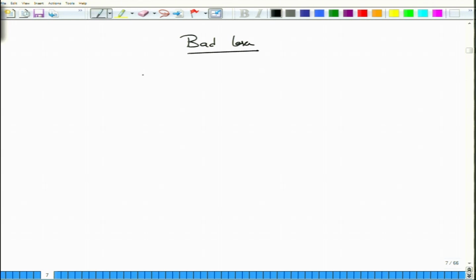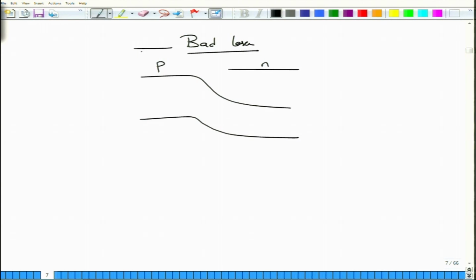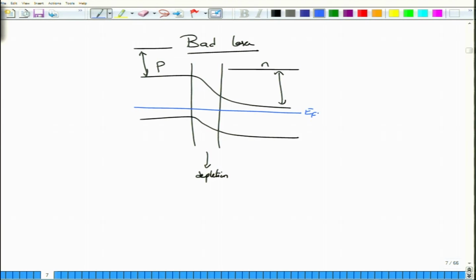You start off with a PN junction. So, you have a P region and an N region here, and this is an energy band diagram that you already know. Somewhere above will be the vacuum level. We have already talked about those vacuum levels. And this of course is the energy gap that you have. This region in between is the so called depletion region, under the equilibrium condition. Under the equilibrium condition, you have the same Fermi level everywhere. It may not show it correctly, but this is how the Fermi levels are present.